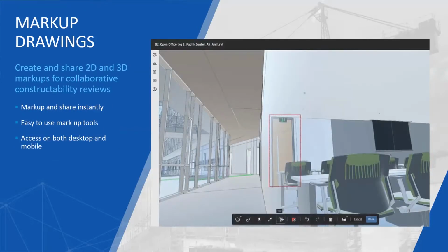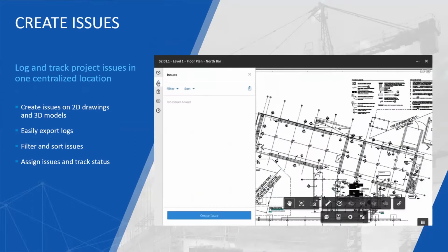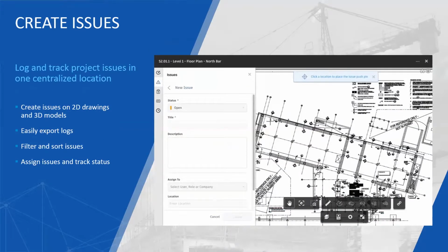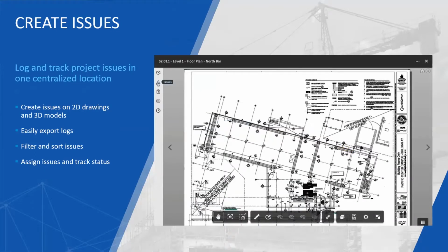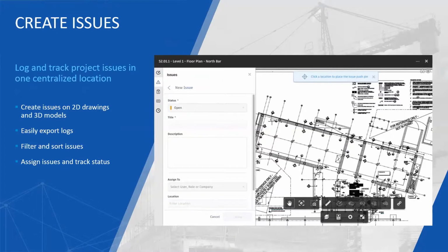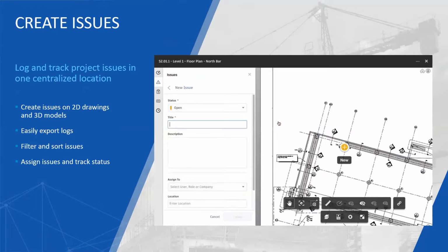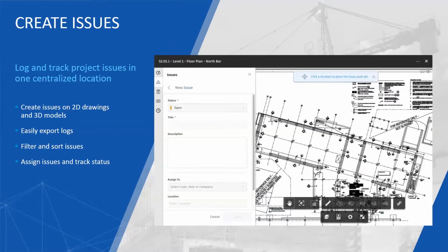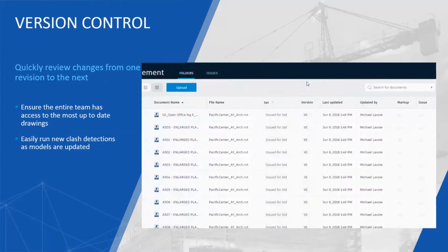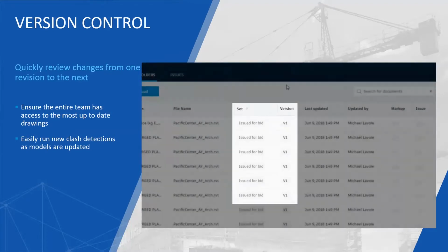Other things you can do: also mark up drawings. As I showed already, you're able to add comments to these drawings, and again assign that to people within the 3D model viewer or even just on 2D drawings. So once you find design issues, you're able to assign those to particular people, and this can be done on PDFs, or on a Revit drawing or a DWG drawing, or another of the 50 file formats that it does support. And this just allows you to manage your project, I suppose, in a more central way at the design stage.